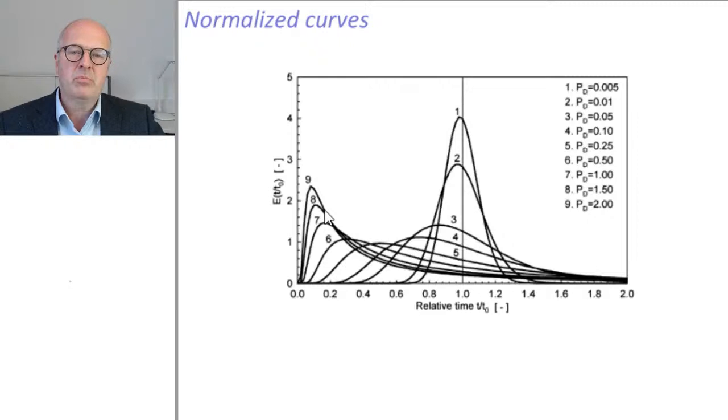And this is what we call preferential flow. And this is why it's so interesting, because it is actually quite typical and happens quite often and surprises us in natural systems. So some systems have preferential flow, and this just means that there are flow connections with high flow velocities. They do not represent the average residence time, but they can lead to early peaks, early breakthroughs that surprise us.